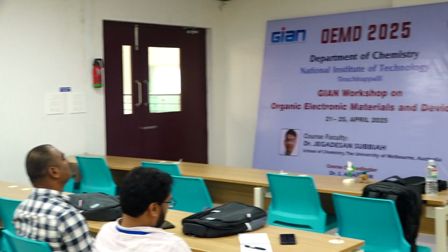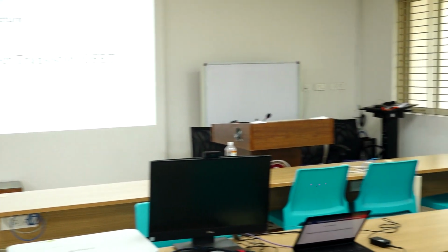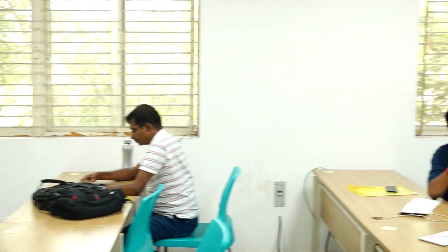Any questions? Yeah, contact. No, no, that is different. The external contact is different. Yes, we are exciting it, and that's important. There we need at least a low work function for electron extraction and a high work function for hole extraction. That one we can fix, we know the work function of the metal, it is already known. Only the new material here is organic, and that one we don't know, so that one we have to find out.